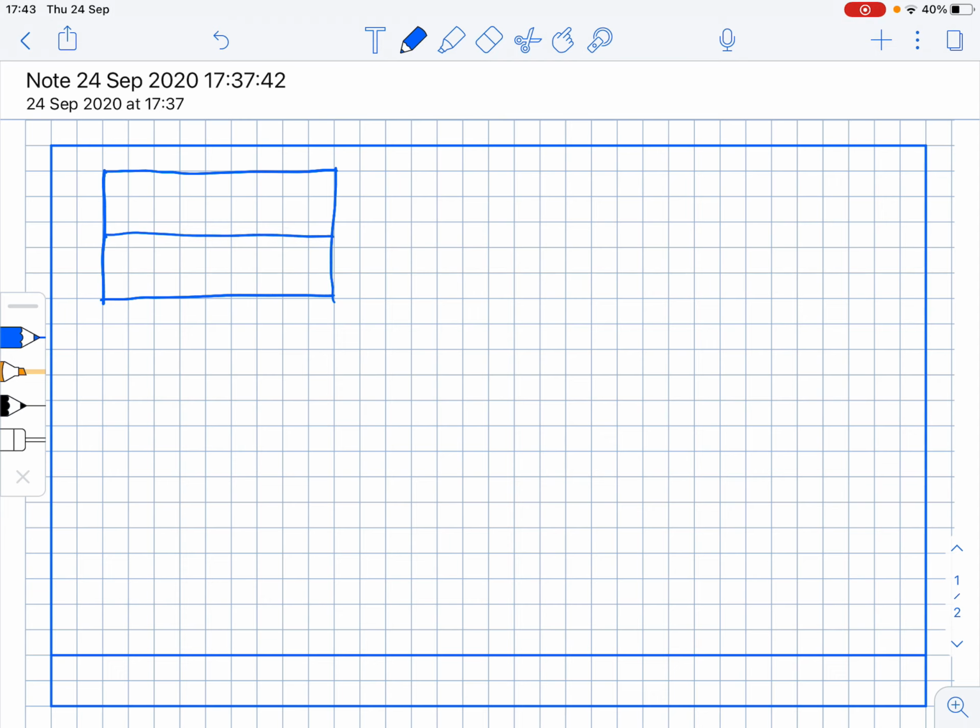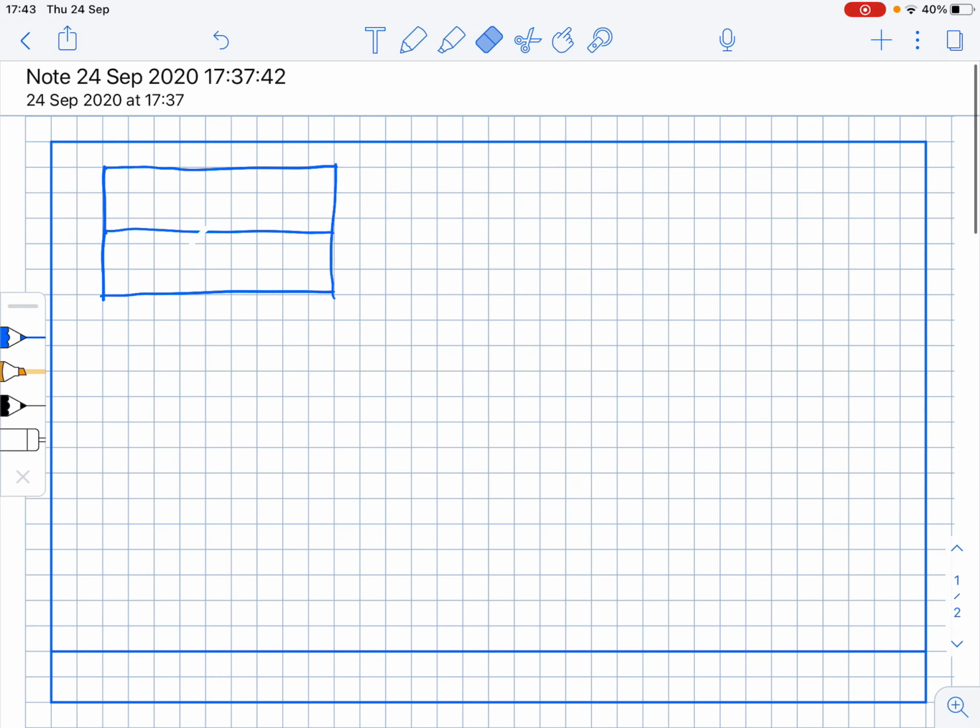However, it's got a hip at one end, and you'd have found out that a hip doesn't look like that. So you would actually move some of this, and you would have a line coming up at 45 degrees, crossing there, and crossing here, joining there, and coming back. So that's what the hipped roof would look like from above.